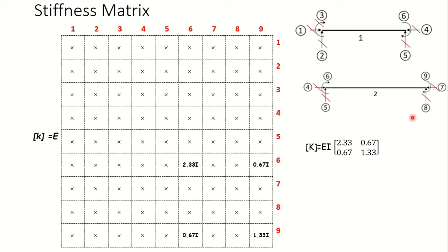Now coming to the next joint, that is joint C. Here 7 and 8. 7 we are not interested in, axial deformation will be negligibly small. So seventh row and column values will be deleted over here. Similarly, eighth, there will not be any displacement in the vertical direction because of that support. So this eighth row and eighth column will be deleted. Ninth coordinate corresponds to rotation. Yes, rotation is allowed at that joint C. So we are going to retain the values of 9 9.